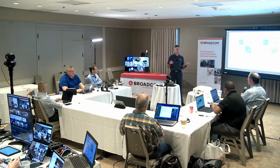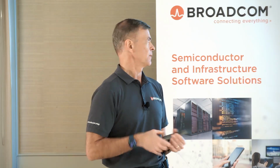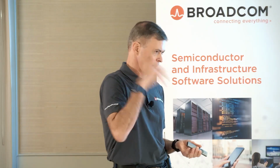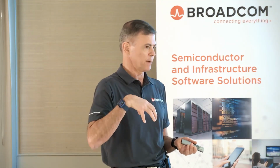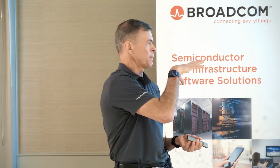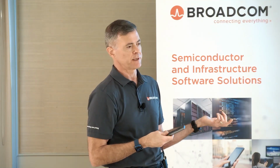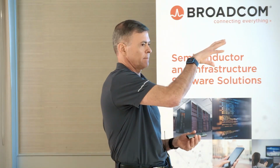Yeah, and you can do that. I mean, you can also just use RDMA right now, where you're bypassing the stack going directly to memory. In this case, it's actually going to be a bit more direct path, yes, because the CPU is not involved at all. So there is no stack. It's basically the native NIC interface sitting right next to your training ASIC, just dumping the data to and from the native memory for that ASIC. So you could, for example, have an ASIC that's got HBM, and then you'd have the NIC interfacing through the ASIC, directly to that HBM.